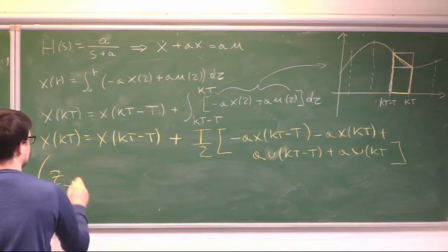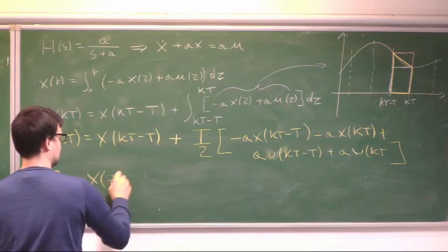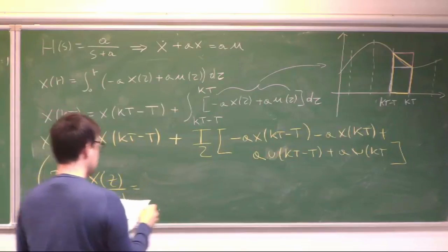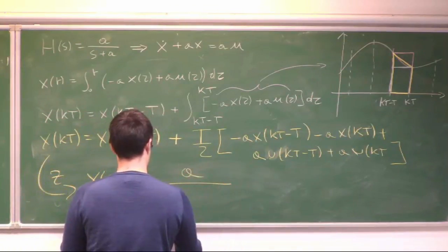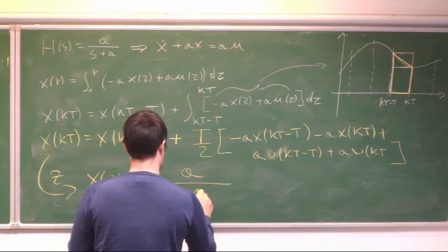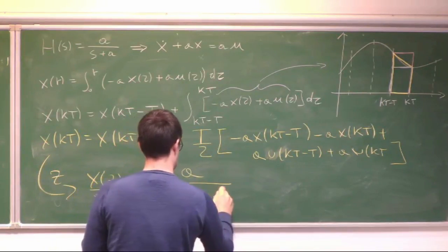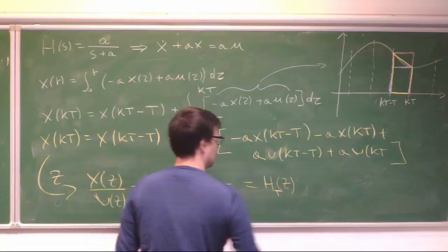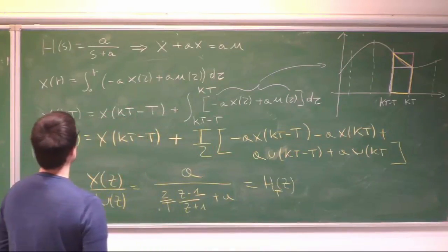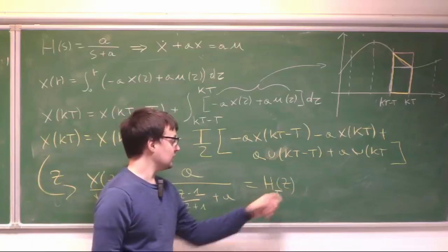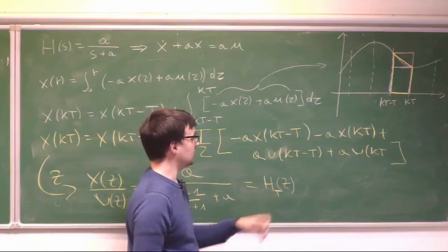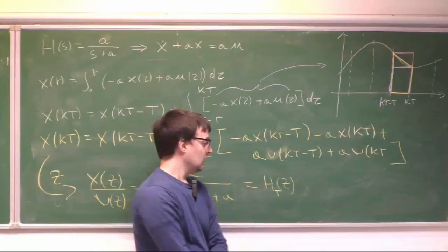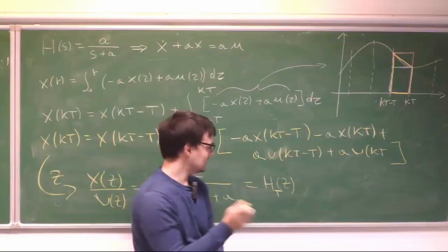Again, we compute the z transform, and then we compute the transfer function between X(z) and U(z). And what we obtain is the following. Okay? And we call this H_T(z) with a little T over there. The reason we call this H_T(z) is because we are using the trapezoid rule, or this is also called the Tustin rule, or is also called the bilinear rule. So it has different names.